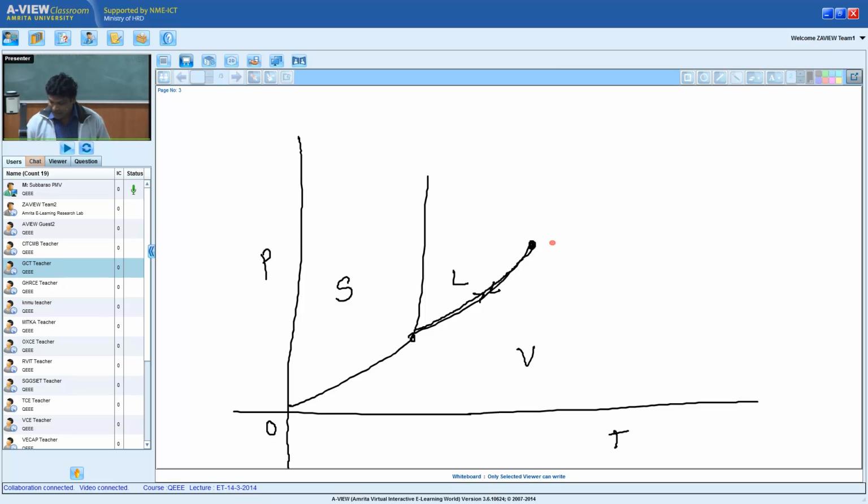There is a destination after which you don't see any difference between the liquid and vapor. What does it mean? If I go on adding heat above this particular point, temperature will continuously change. I'll never get such a dilemma as I was getting, where temperature increases up to some point, and then though I am adding heat, temperature doesn't change, only volume changes.